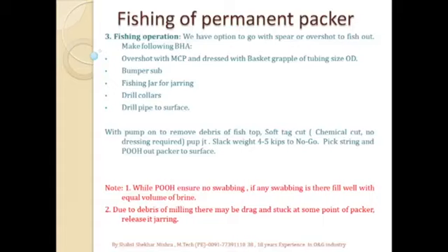That we can release by working the string, by jarring or bumping down. And this way we can recover and pull out the permanent packer to the surface.